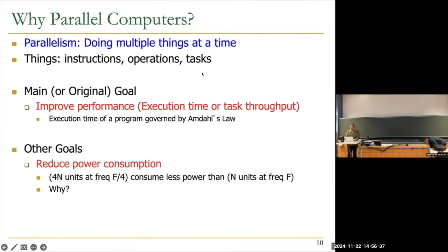Yeah, basically, as you have said, the basic reason is at least dynamic power is equal to C V squared F. Well, I guess I wrote large F. So if you reduce frequency, clearly this reduces, right? Now, if you reduce frequency, you can also reduce this because you don't need to power your circuits as much with high voltage. And now this reduces. Now you have a quadratic effect, right? Or cubic effect. Once you reduce your frequency, the power reduces actually cubically.